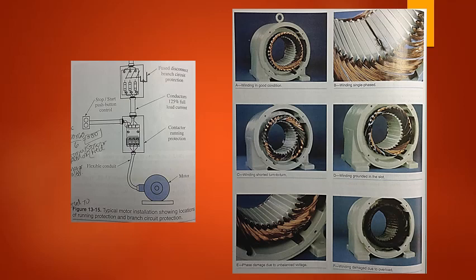Low voltage. Another common cause of excessive motor current is low voltage. Under a low voltage condition, a motor will maintain its horsepower output rating until the low voltage becomes so severe that the rotor locks. This low voltage condition causes excessive current in the windings while the motor is under mechanical load. Remember, when checking for low voltage conditions, the motor must be under mechanical load, otherwise the voltmeter readings will not be accurate.